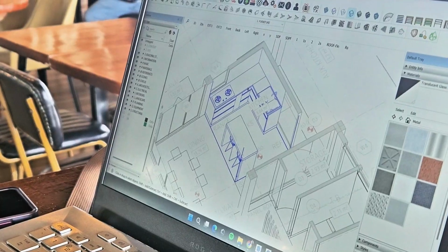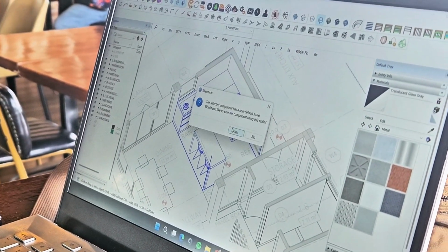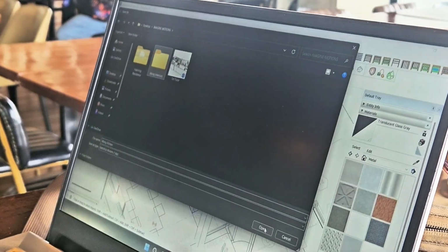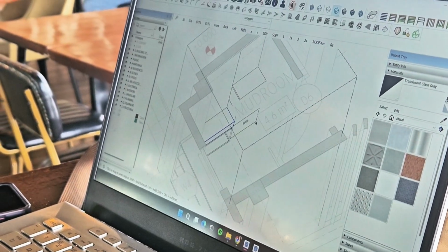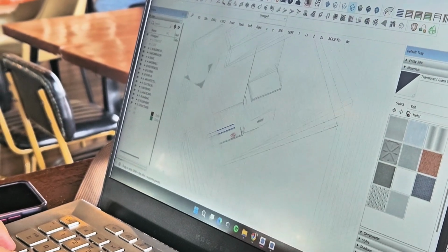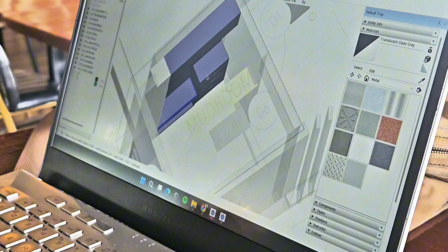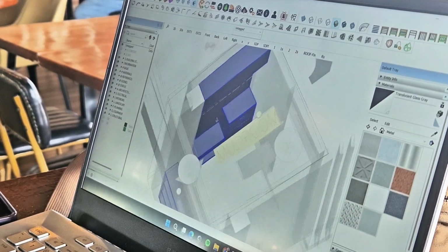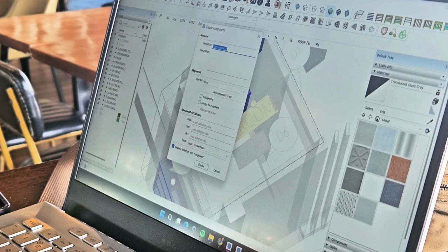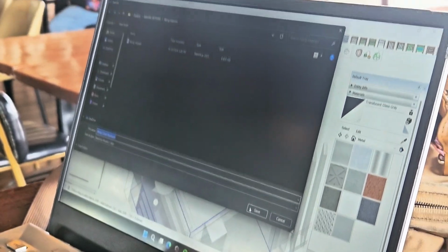Right-click the component. Save as. And then save it in a folder on your desktop. Inside that folder, and save. Shift S so you can see the whole model. Can you see it? And then make it colored. There. So everything's selected on that wall. Right click, do the same thing. Right click, save as. Just press enter. It's going to go to the same folder.